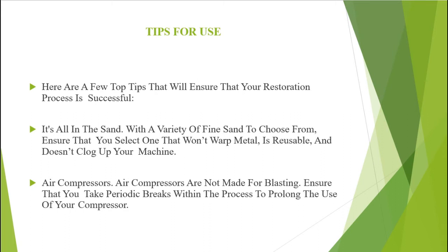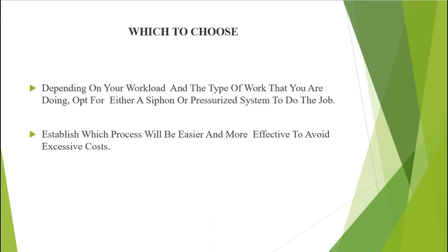Air compressor. Air compressors are not made for blasting. Ensure that you take periodic breaks within the process, which will prolong the use of your compressor. Which to choose depends upon your working load and the type of work that you are doing. Opt for either a siphon or a pressurized system to do the job. Your process will be easier and more effective, avoiding excessive costs.